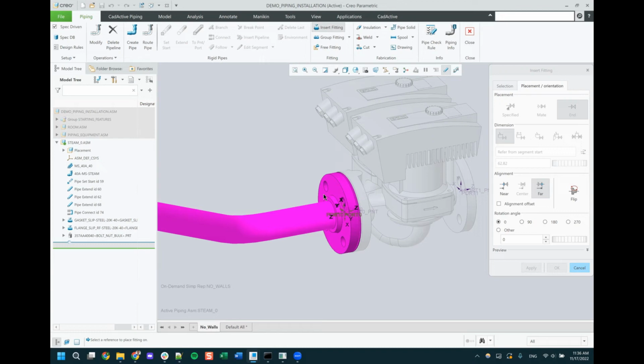In a really large assembly, if you have detailed threads on your bolts, that's really going to drag down your model performance. We don't have to actually represent those graphically. We can use this bulk part, and the information about what is included there is going to be stored as parameters on this bulk part. So when you go to get your bill of materials, all of that information is still going to show up, based on being stored in this bulk item in the parameters. So that's one thing. That was the first drop down there.